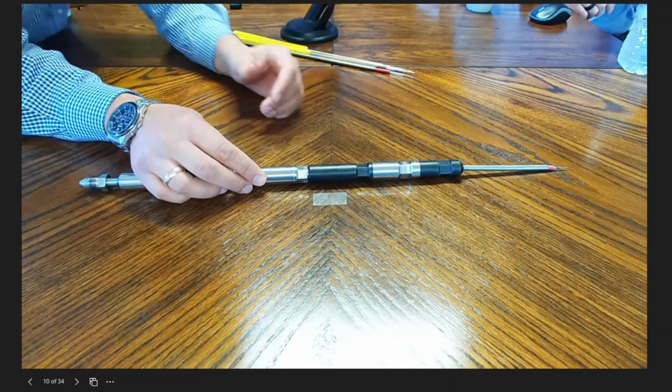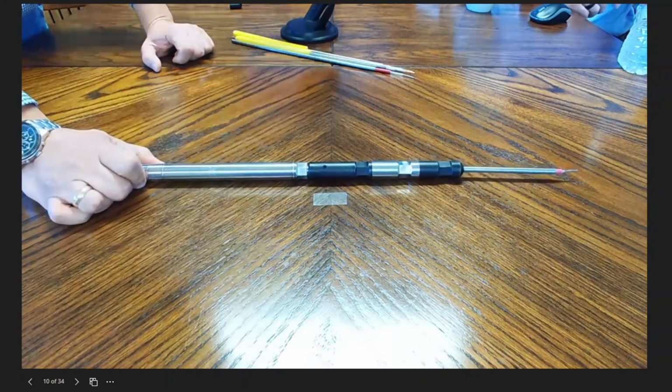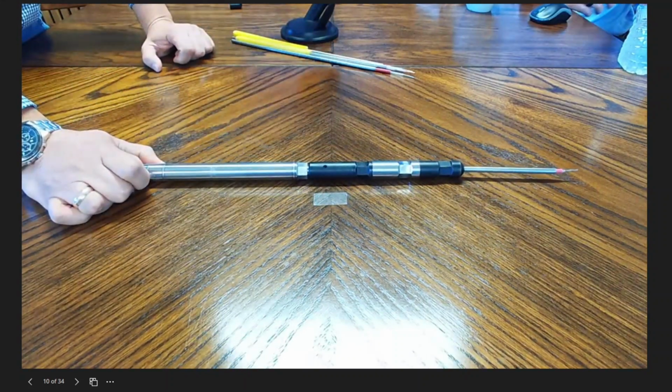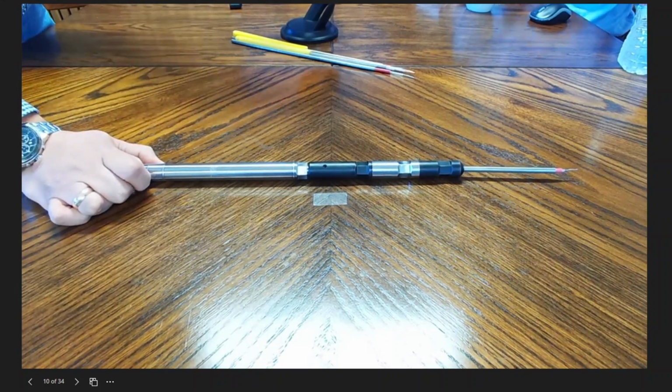Okay, and if we just use the example well of say 10,000 feet, you're going to be roughly around 5,000 PSI of hydrostatic at that depth. So you're pressure testing above what the probable environmental pressure would be once the gauge is downhole. Correct. Yes. You want to make sure all the seals are functional at higher pressure.